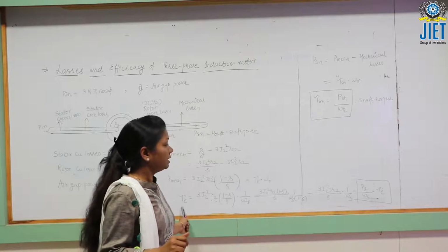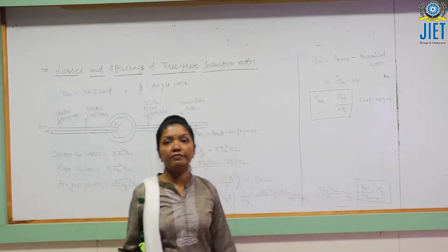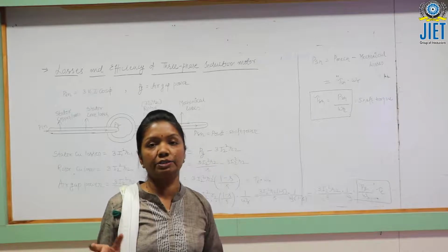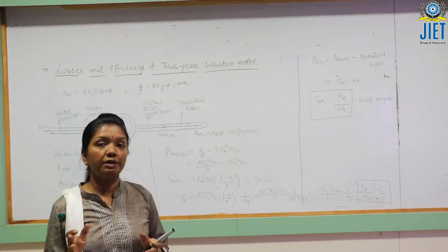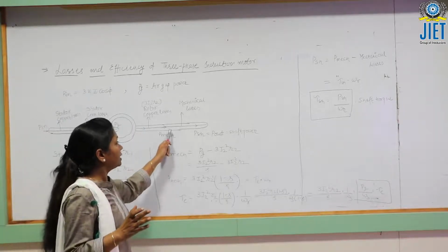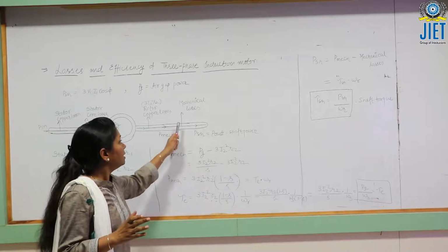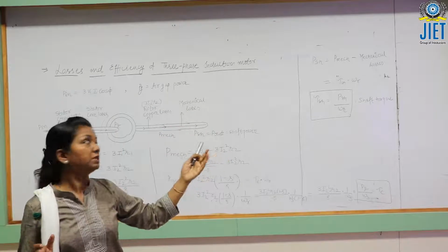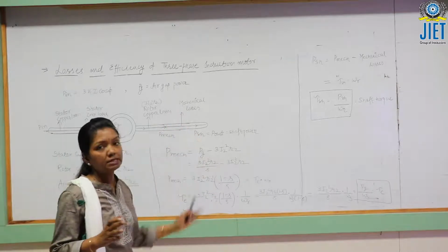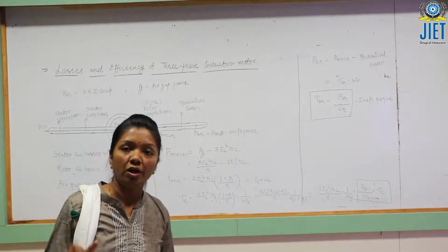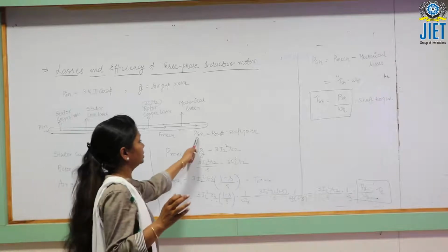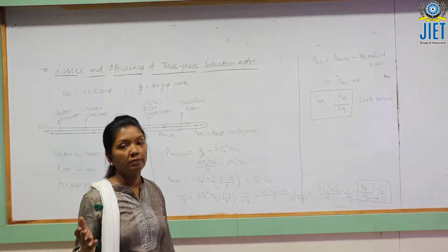Pg is the air gap power, and omega S is the angular synchronous speed of the stator of the motor. By substituting the elaborated value of I2 in terms of the circuit parameters, we can find a detailed expression of the torque developed. For a motor, torque is an important parameter. After power is converted into mechanical, the mechanical losses, which are friction and windage losses, occur, and the power left after these losses appears at the shaft, called the useful power, shaft power, or output power. All are the same.